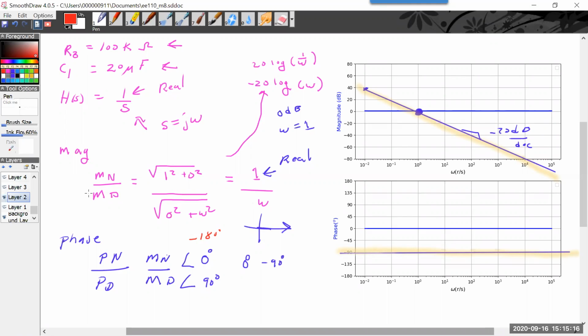Okay. Or actually, it's really plus 180. Because when you take 180 minus 90, the phase would become 90. And that's what LTspice and the Python packages will do. So you probably just have to know that minus 1 becomes 180.